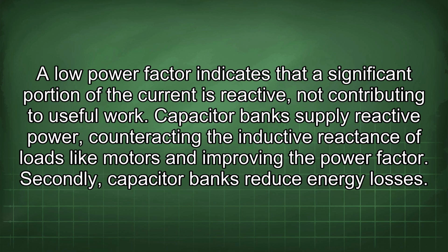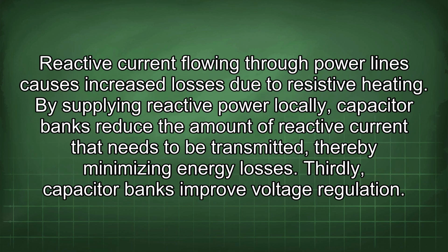Secondly, capacitor banks reduce energy losses. Reactive current flowing through power lines causes increased losses due to resistive heating. By supplying reactive power locally, capacitor banks reduce the amount of reactive current that needs to be transmitted, thereby minimizing energy losses. Thirdly, capacitor banks improve voltage regulation.